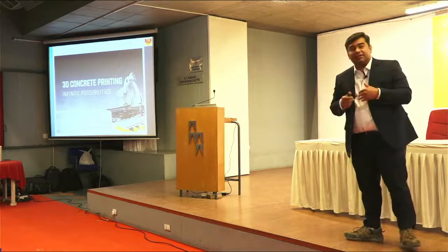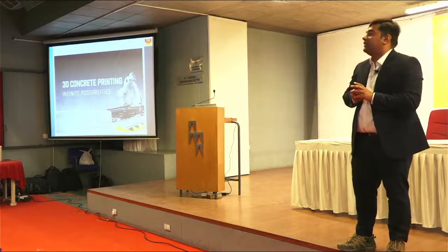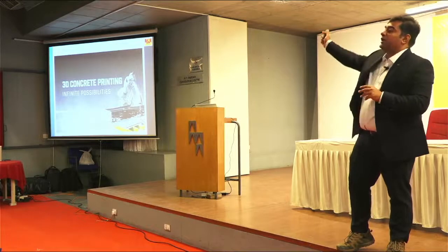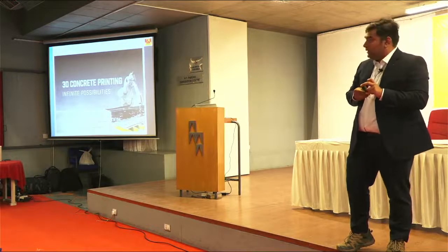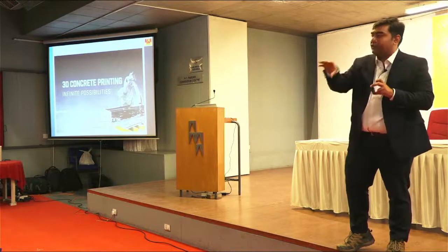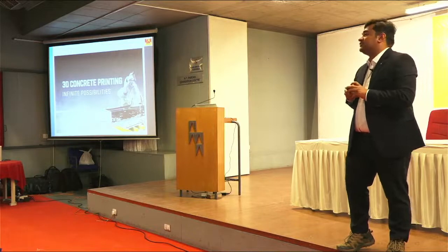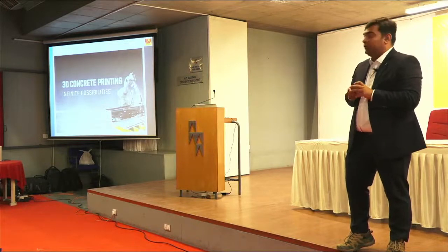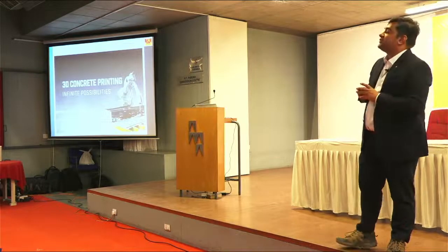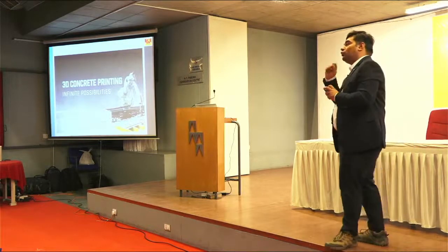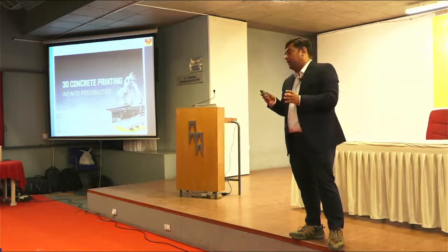And as I have said, all the steps have already been covered, and these 2 steps will be covered in the near future. This 3D concrete has strength around 50 to 60 megapascal, and the extrusion process, also the mix design, is on the basis of yield stress. You might have heard of yield stress. So this design is based on yield stress. It has no coarse aggregates, only fine cement and water.